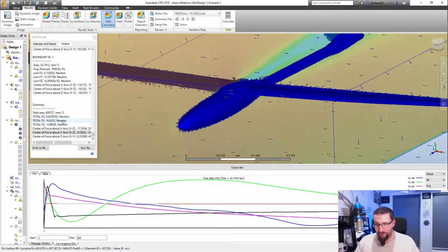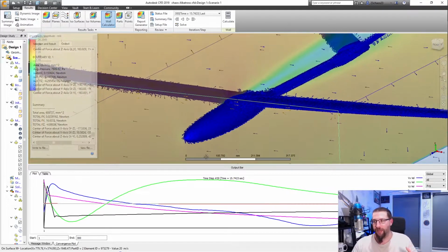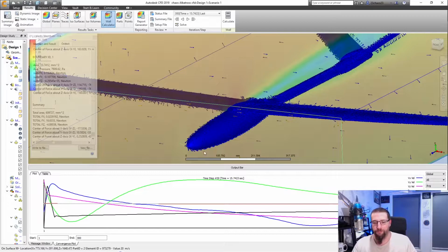So it's got more than enough lift, and this is at neutral, right? This is 0 angle of attack, and it's going to cruise at 20 meters a second. I'm going to need to now run some simulations at 10 meters a second, so I can see how it starts to perform at lower speeds. 20 meters a second is not the fastest that I can go with this prop. This is a 6-inch pitch prop. One of these produces roughly 1.5 kilograms of thrust, and my all-up weight's going to be 1.2. Let's say 1.3. So I've got a 1-to-1 thrust to weight ratio on this thing.